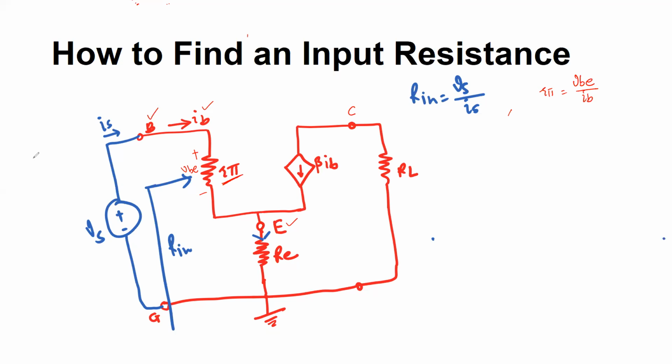Now, when you want to use it as a small signal amplifier, you basically use this current dependent current source, whose value is beta times the input current IB. And this is essentially a current that is flowing from the collector pin of the BJT.